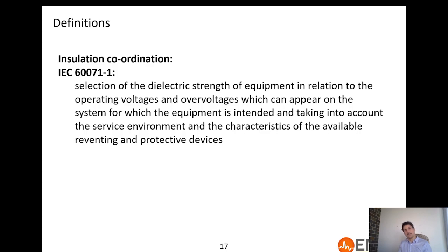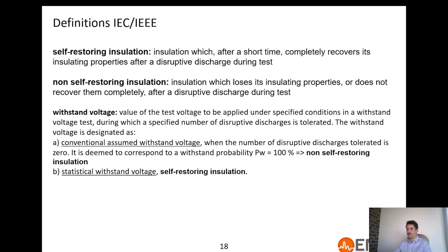What we are going to see is that from some studies, it's not possible to be 100% sure that you will never have a failure. Instead, the outcome of the study will be the mean time between failures, which will be, for example, 50 years or 100 years, which means that you will expect a failure statistically every 100 years, and economically it makes sense for you. So sometimes you will have on and off results, it's designed properly or not. Sometimes it will be statistical, and we'll have to take a decision based on equipment cost versus risk of failure.